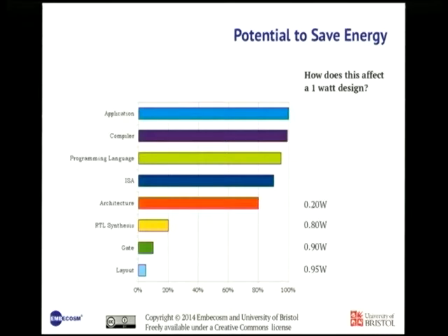We start thinking about the architecture, how do we design that cache and that pipeline? That's when you start to make big savings. And you can potentially get down to a fifth of that. So instead of your battery going flat in 1 hour, it goes flat in 5 hours. But we think when you go above there, better instruction set architecture, you can probably double that. Now I've got a 10-hour battery. Better programming languages, where I can say, this doesn't matter, you can do this in low energy, this thing's got to be done quickly, burn a bit of power to get it done.